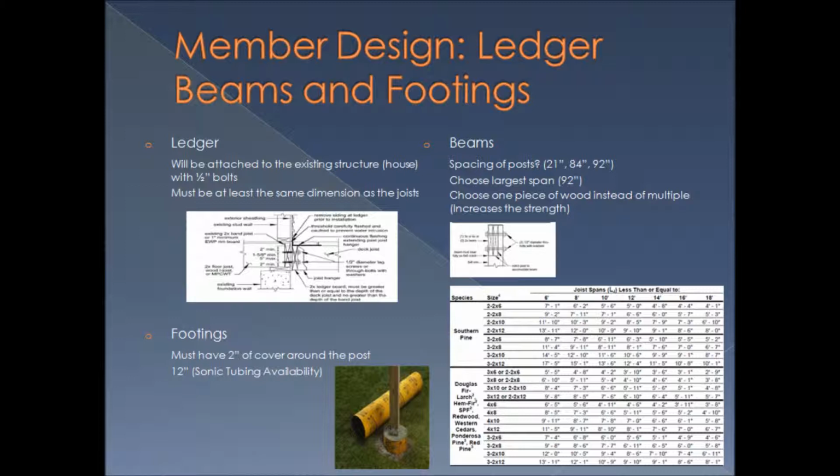Now for the final structural component, we'll make our way to the design of the footings. These are the final step in the load transfer. These are the base of the structure and consist of concrete, as I mentioned earlier. As long as there's at least 2 inches of cover around the post, the sizing of the footing is good. And what I mean by cover is, you have the post and that goes on top of the concrete. 2 inches of cover means that there has to be at least 2 inches between the post and the outer part of the footing.